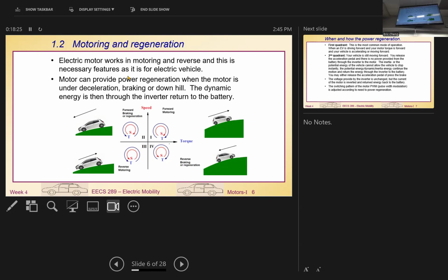For instance, when you control the motor forward, like this, if suddenly you turn off all the transistors, then the vehicle will still try to reduce the speed because it still has some momentum going forward. But the gravity will pull you downward. So then it looks like we are now using the gravity to power regen to store, return some energy, reduce the speed back into the motor. So we'll show you how to use transistor to control this tool.